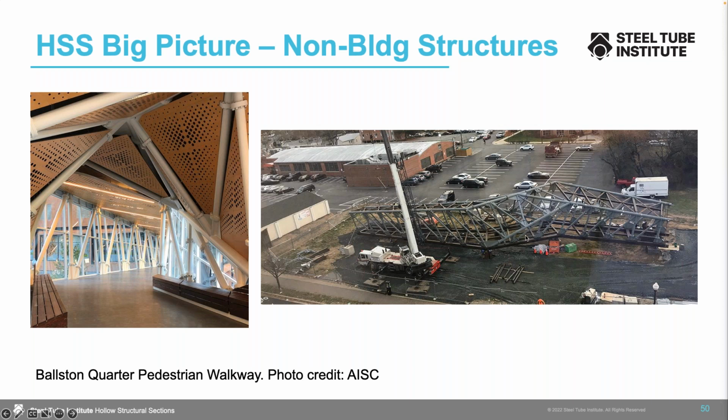Not only does it twist, it's supported in the center and the sides cantilever. So that HSS frame provided the necessary rigidity to minimize deflection and bounce for pedestrians who were walking across that walkway. And of course, it just looks cool.